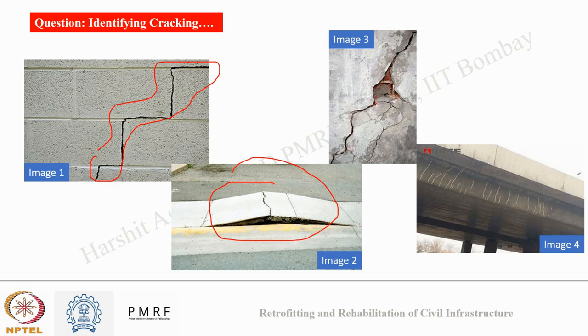So you can see an underlying brick wall, and over that a concrete cover was there. Now this can occur due to contraction or expansion in the building materials, which resulted from fluctuation in temperature or even moisture content. So you can see some moist patches here, also some moist passage, so that can also be some reason behind this form of cracking.